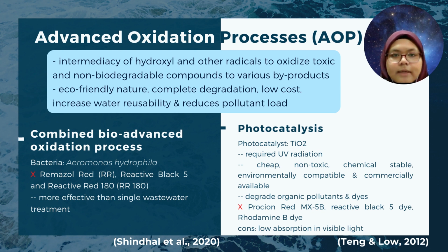Firstly, the combined bio-advanced oxidation process. It is a combination technique with bacteria treatment using Aeromonas hydrophila. It was studied that this method helps degrade Remazol red, reactive red 5, and reactive red 180. This technique is also more effective than single wastewater treatment.